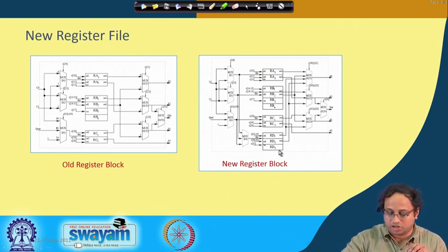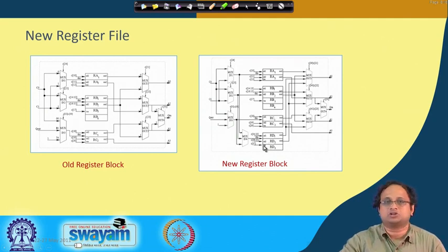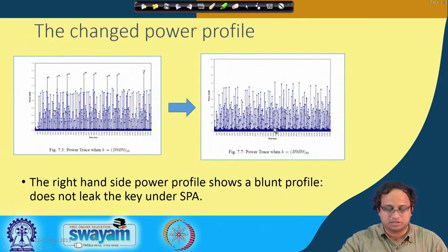Now you will see that this dummy register we have introduced, or rather a temporary register, which is storing the value of your doubled output, also needs a multiplexer at the input, and needs a few additional lines to get the result out to the output port. So these multiplexers are also a little bit widened up, because now you need these register outputs to be channeled outside. So there is a cost that you need to pay.